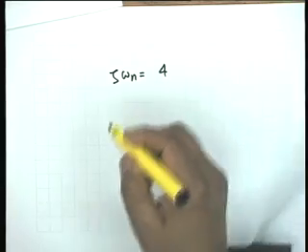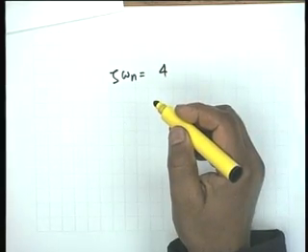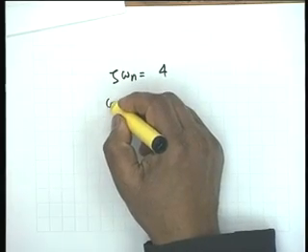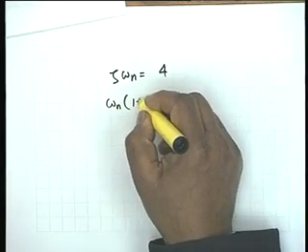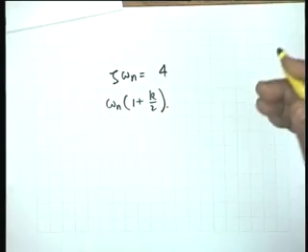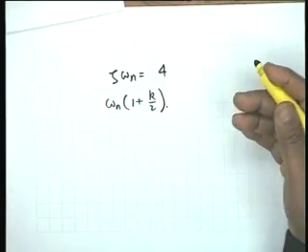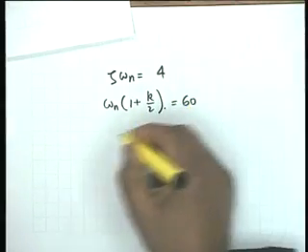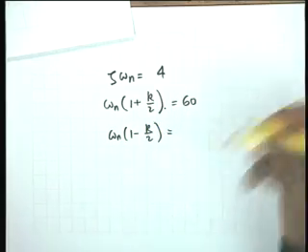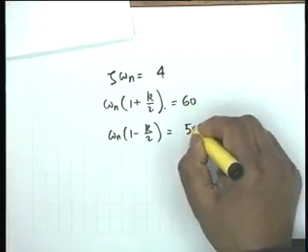Agreed? Then from the high Q approximation, loose coupling and high Q, we get omega n (1 plus k by 2), that is the upper pole in the upper S plane, is equal to 60, and omega n (1 minus k by 2), the lower pole in the upper half plane, is 50.